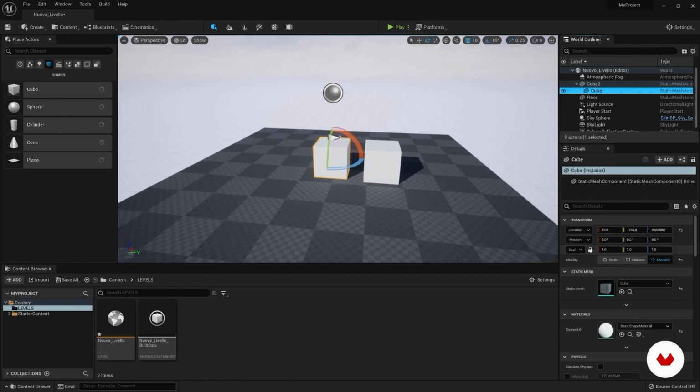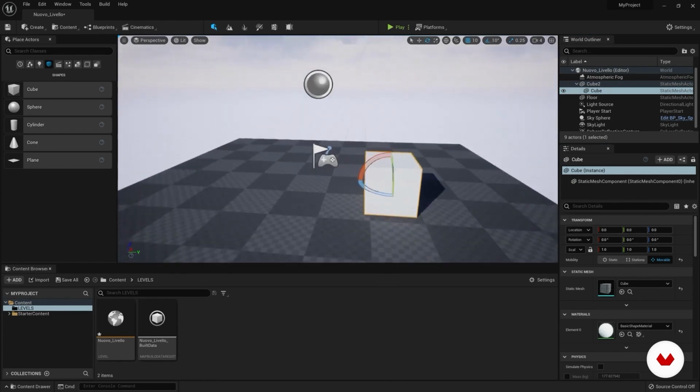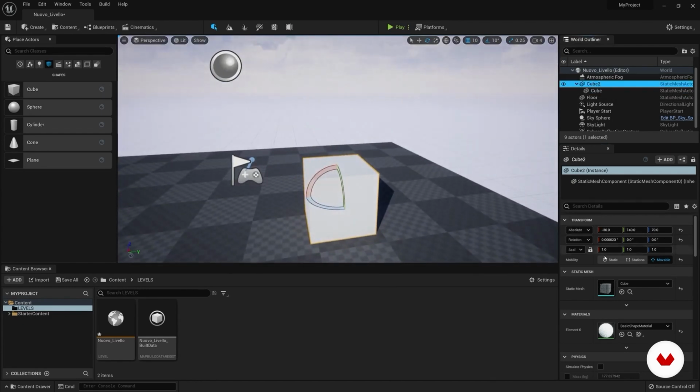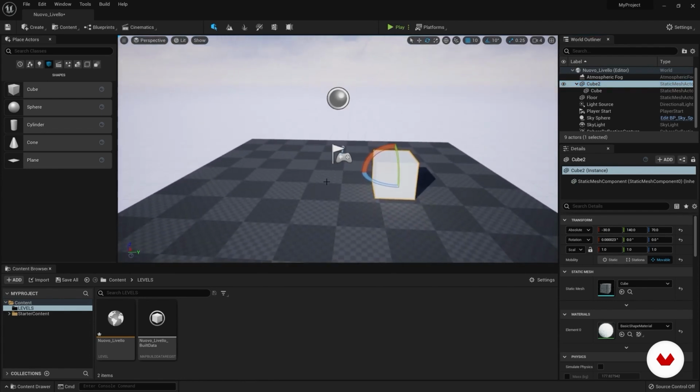But if we set this value to relative, we will see that the values change, because being a child of object 2, these parameters refer to the center of the cube of which it is a child. To be clearer, let's reset all values to 0, and we see that cube 2 has the right world values with respect to it. Cube 1 has 0 values, because it is exactly in the center of cube 2. I hope it is clear. This is very useful during the animation phases.